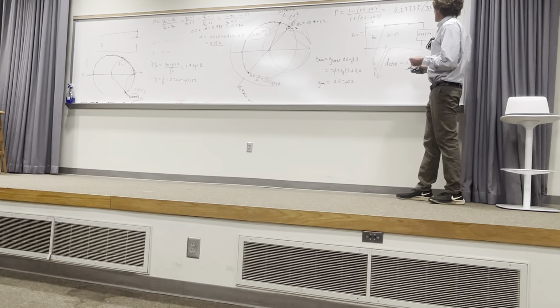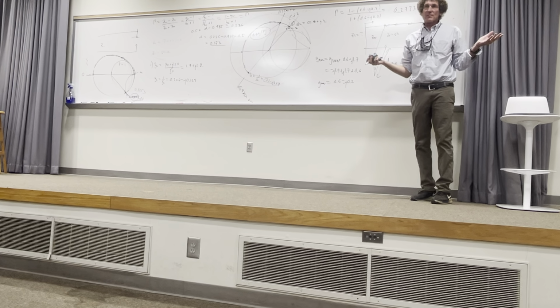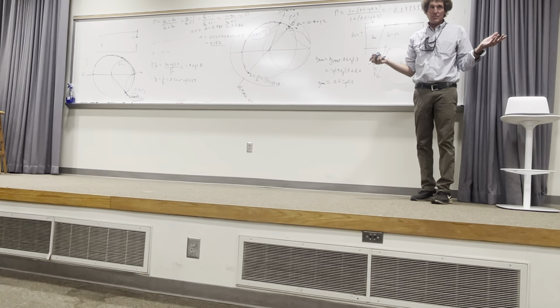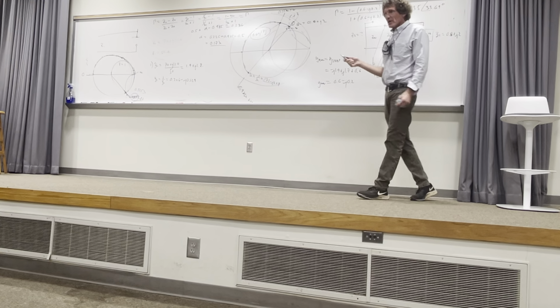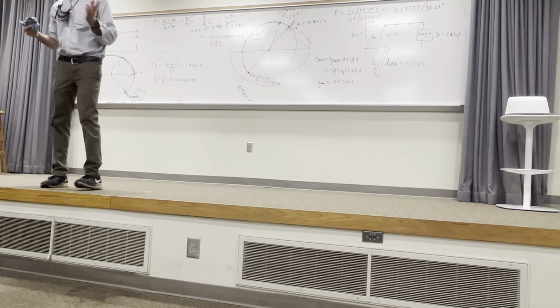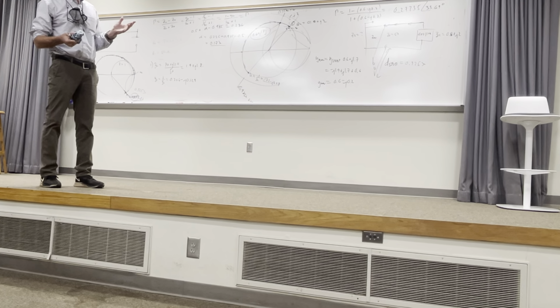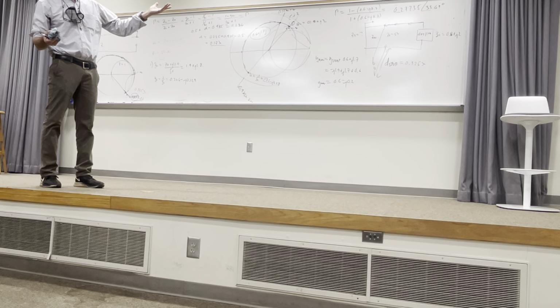0.28277, and that's slop. That's just there, your eyes, you can't help it. You all with me on this class? But that's a good problem because now we matched it for one load, we replaced that load, how bad is it? Well, that's the new reflection coefficient. Actually, that's pretty bad. You're almost 25% for the value, a quarter. That means your standing wave ratio is over 2. That's not good. Anyway, y'all follow how it's done.